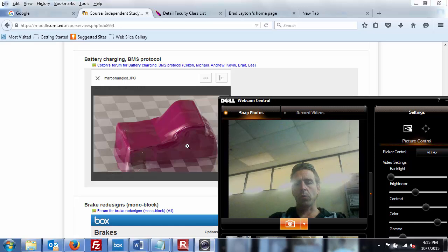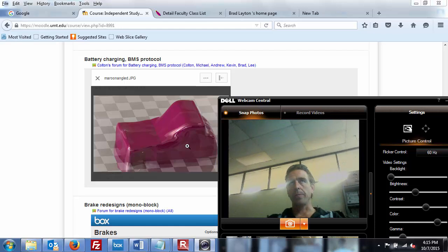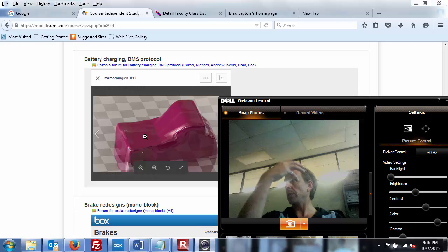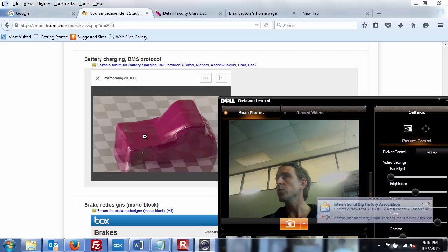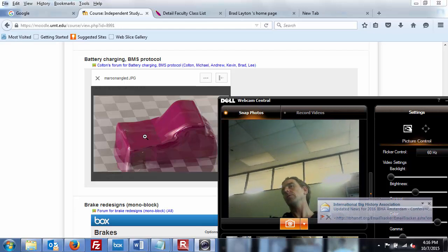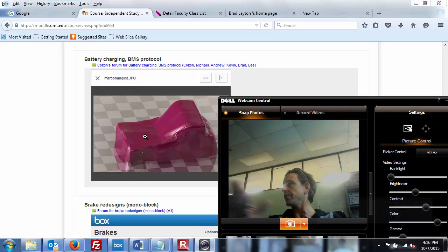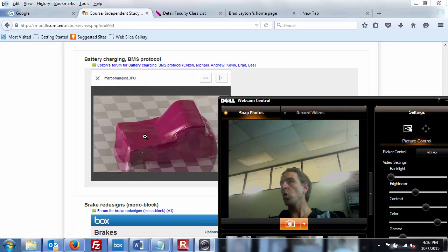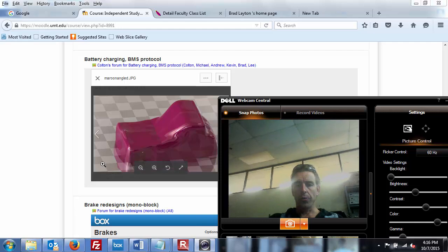If we're getting fancier, what we would do, and it's kind of six of one, half a dozen of the other, would be to make a female mold. So you remove the inside, and then you do your layup inside the female mold, and then you can vacuum bag it. However smooth you make that female mold is exactly how smooth the exterior of the body will be. So it's superior in a lot of ways. You sand the mold once, and then you can just keep using it, and the inside is smooth. I've used that in the past and it worked pretty well.